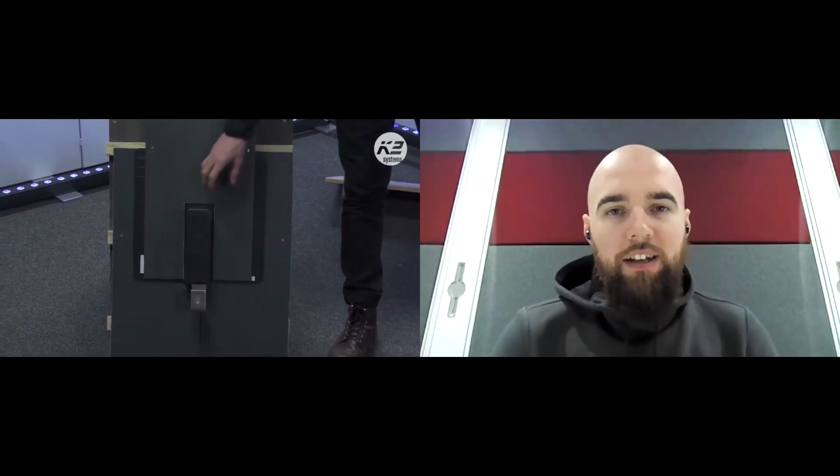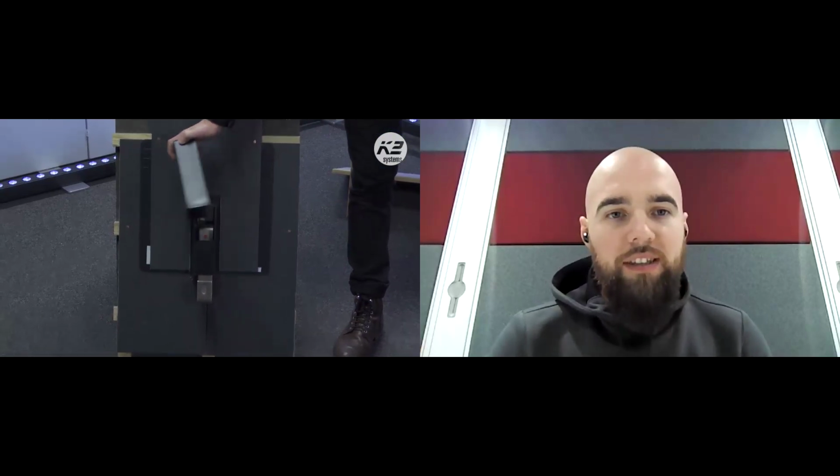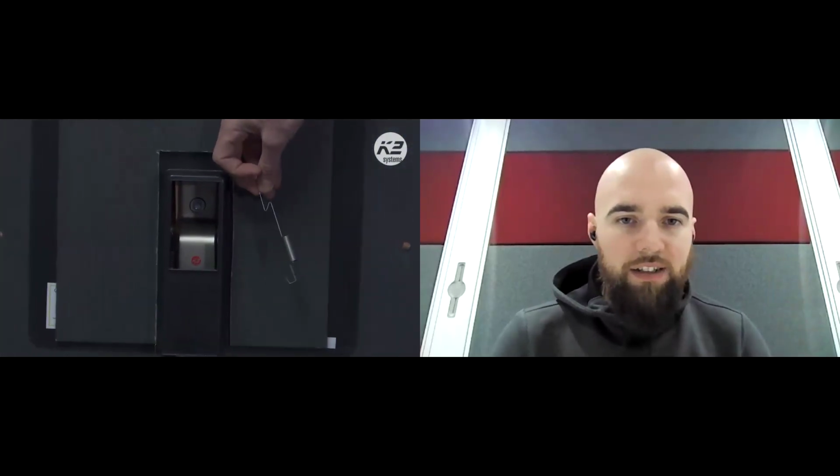And it comes with a spring hall clip, which prevents the actual plastic from sliding, though you'll find that when you slide it up there, it's not going to go anywhere, but that's just a nice extra precaution. And that just hooks into the tile above. You won't be able to see that because that's underneath the actual flashing. And it also comes with a couple of spacers and a foam insert which prevents any water ingress, should any winds push water up towards the actual roof. So that's all included with that.